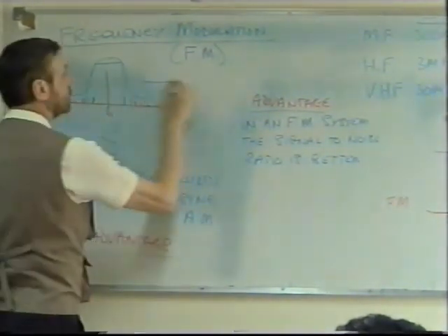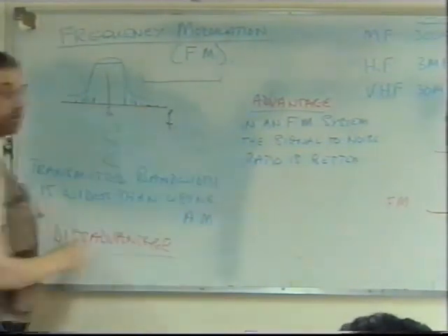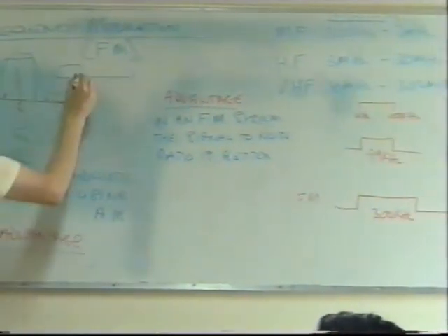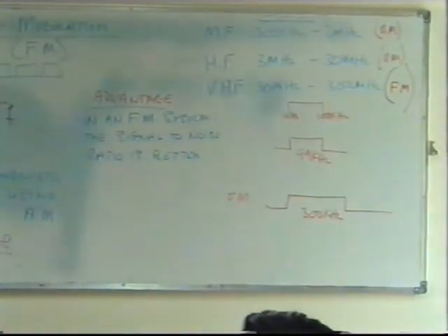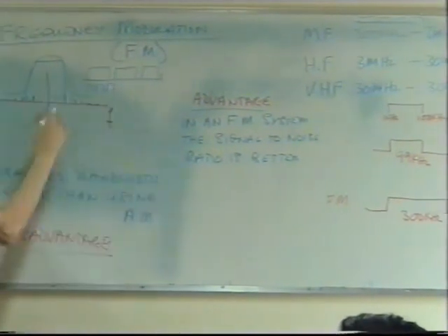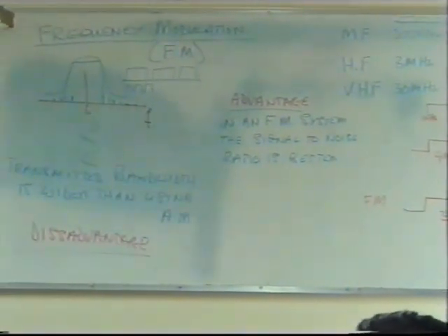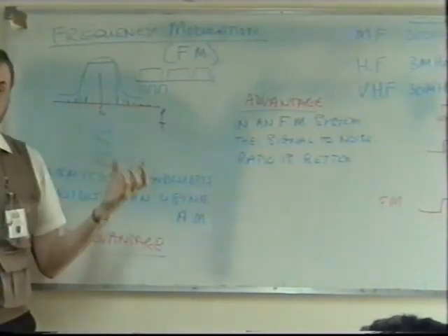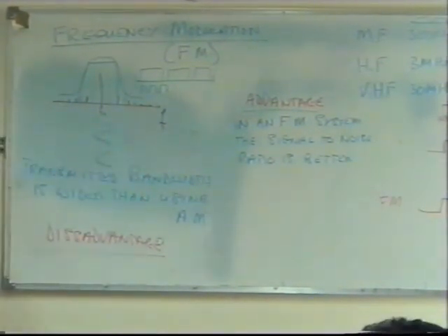Now, let's say I've got a certain band of frequencies. The bigger the bandwidth of any one channel, the fewer channels you can fit. If you use narrow bandwidths, then of course you can fit a lot of channels. Do you see the difference? Don't get the two confused. This bandwidth here refers to the bandwidth of the channel. One channel.